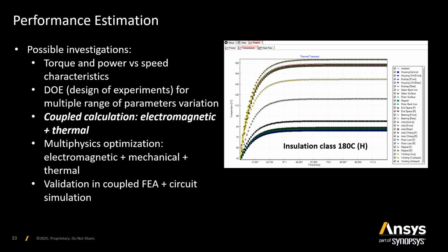This will impose an insulation class for the wires of 180 degrees Celsius, or H according to the previous standard. So this will ensure that this machine can operate and the drone will be up in the air. Here we notice this calculation is done for about 2 hours. So no component will exceed that temperature.